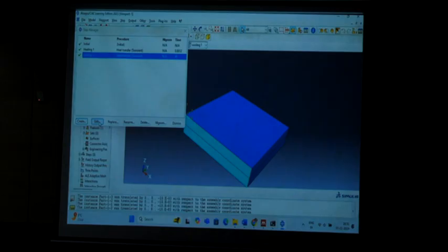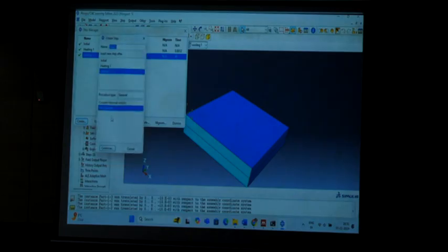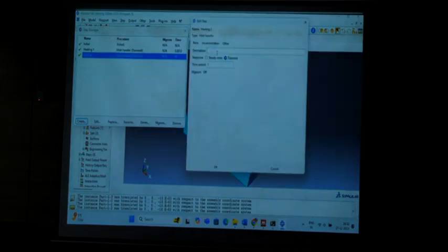In the same way, one more create, because we have two layers, so one more time we have to create, and it will be saying heating 2. Each layer should be given the heat source, and we need to cool it down. Same thing we need to repeat. But the problem is, if you have a larger number of layers, it's better to go for using some code, Python codes, or those things will be helpful for you.